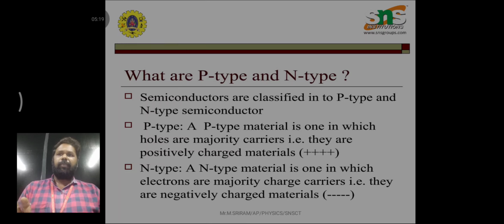That is P-type: replacing one of the lattice atoms with a group 3 atom. We can also replace it with an atom of 5 valence electrons, such as the group 5 atoms arsenic or phosphorus. In this case, the impurity adds 5 valence electrons to the lattice, which can only hold 4. This means there is now one excess electron in the lattice. Because it donates an electron, a group 5 impurity is called a donor. Note that the material remains electrically neutral.